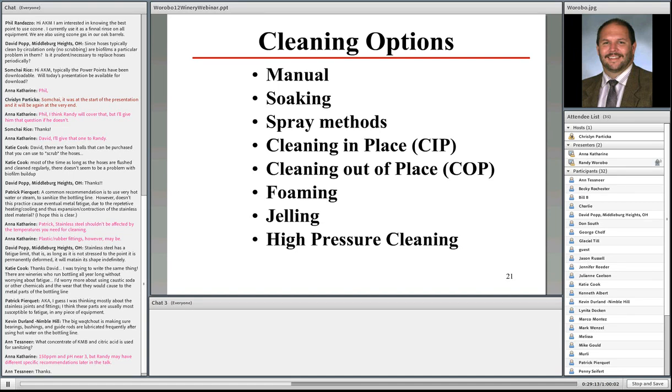There are also some very important things you want to take into consideration, which is to have correct brushes. So for long pieces of stainless steel piping, you can have very long brushes that need to get in. You need to guarantee adequate scrubbing at all locations. There are spray methods. This is where you can apply it through a pressurized vessel. It's not high pressure cleaning. You basically apply it, and it allows the detergent to come into contact with the dirt and then lift it off.